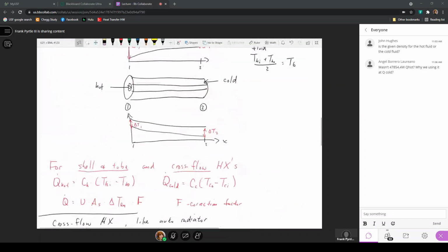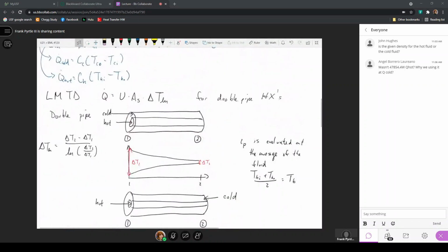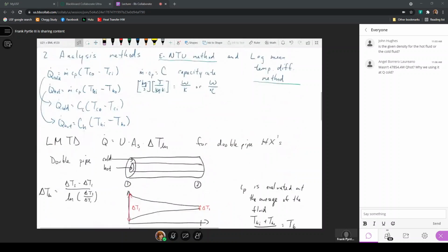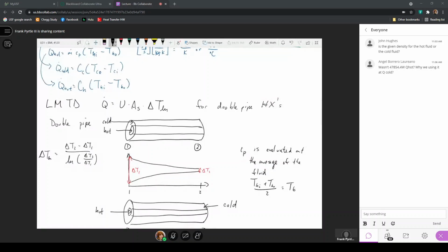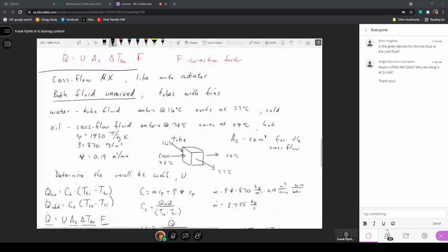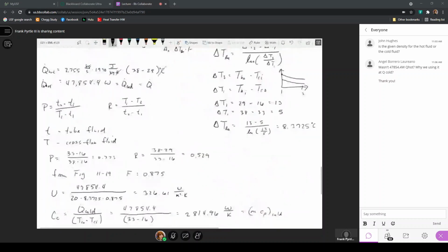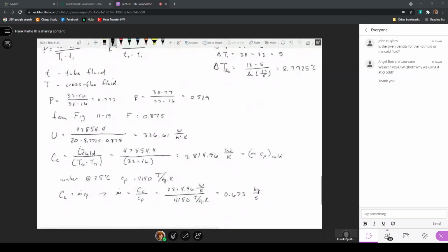It's the concept from when I first started talking about heat exchangers: all of the heat lost by the hot fluid is gained by the cold fluid, and no other heat is lost or gained in the heat exchanger. That is why we can equate these two quantities, and you have to remember that when doing a heat transfer analysis on a heat exchanger, because otherwise there will be unknown quantities you would not be able to solve for.